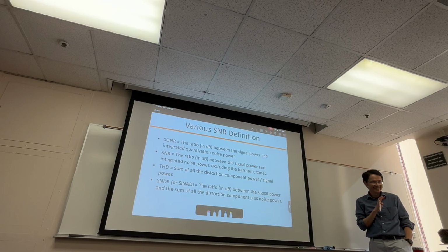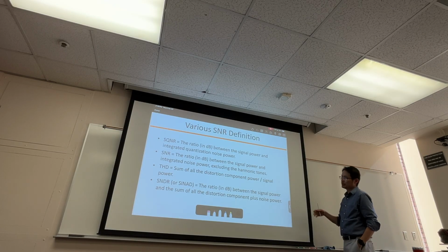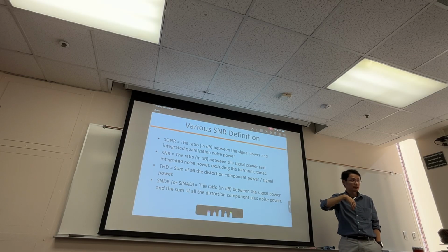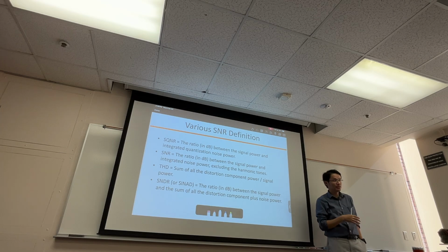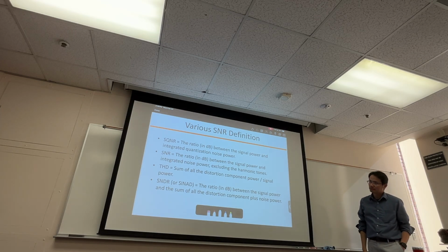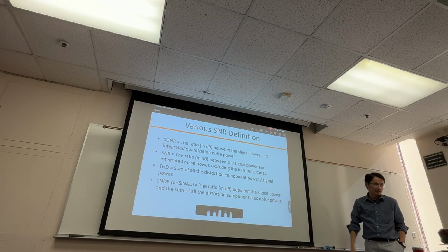So it depends. Typically THD, if you have a tone pop out, typically it will be worse. But who knows? Maybe you design an ADC where distortion is so low, even lower than the noise floor, then you're going to see a better THD but worse SNR.